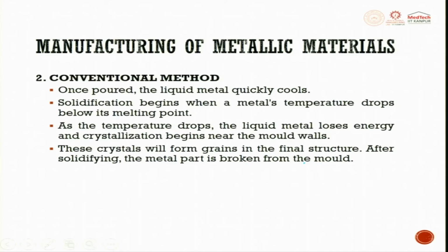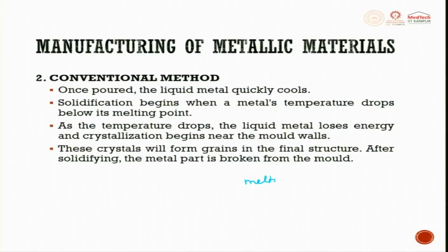So, these are typically the sequence in a casting process. Take it above the melting point, bring it to solidifying, allow it in the freezing temperature zone for some time, and then it gets into the solidifying zone, the material solidifies, and then you get the final part. All these things have to be done in additive manufacturing also, but here it is done on a very small scale. That is why in additive manufacturing we keep discussing the melt pool.